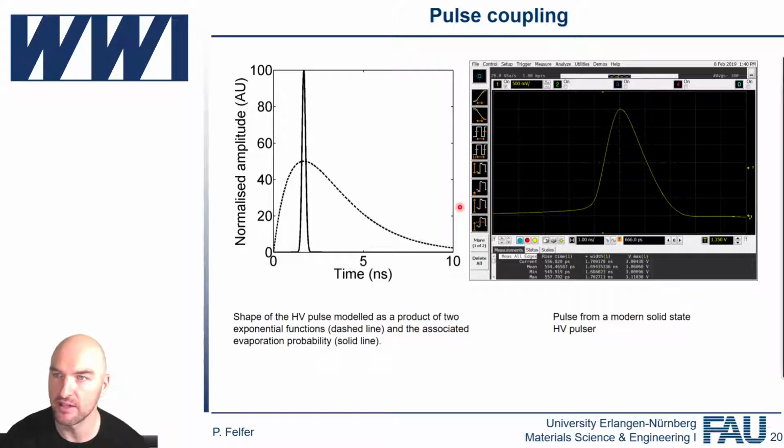Well, you need to attenuate the pulse, because if you put a 3 kilovolt pulse into your oscilloscope, it will just go up in smoke, and it's going to be a very expensive oscilloscope for that purpose. But you put in a series of high frequency attenuators there, and then you put your oscilloscope there. If you want to do that on a Cameca atom probe, you can do it in a variety of ways. You can either connect directly to the pulser with some attenuators. We've done that during some pulser repair back in Sydney.